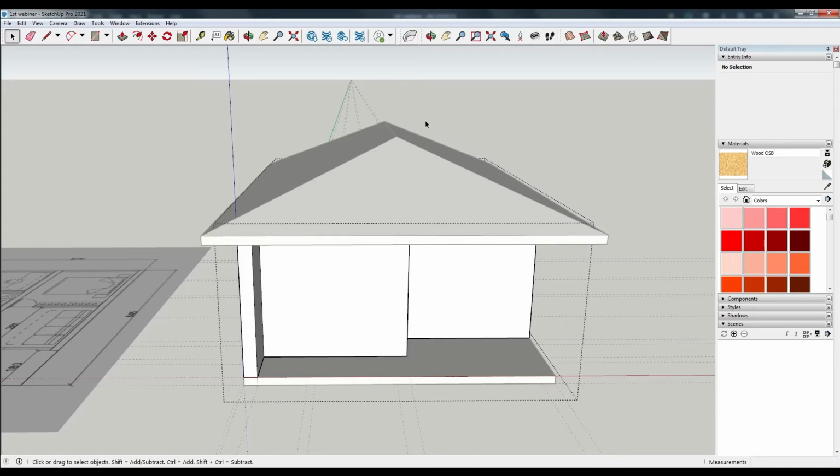So I will choose to work with the group of the walls. I will choose a starting point. Then I will choose a direction and will give the sizes of both length and height. You can see the numbers in the right down corner of the screen as I type them.